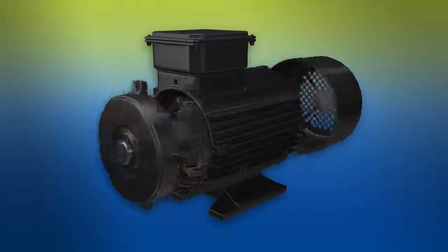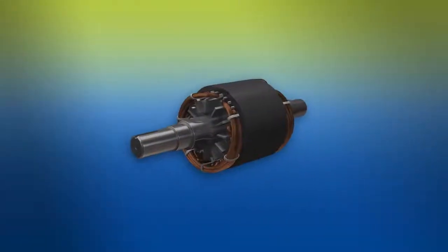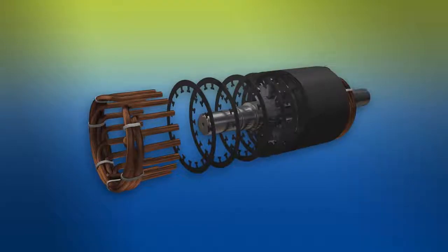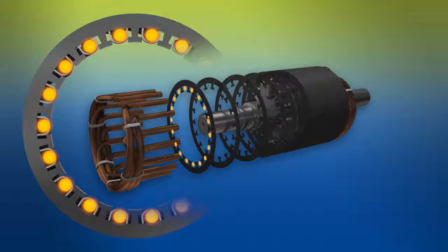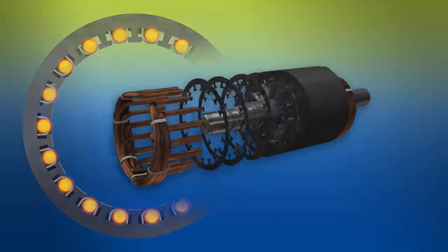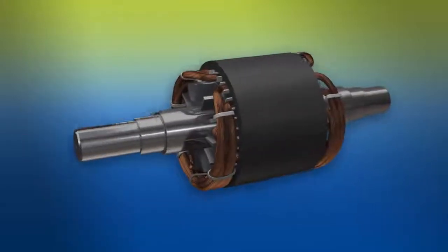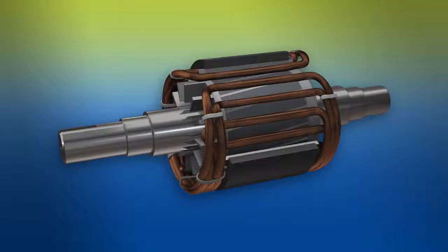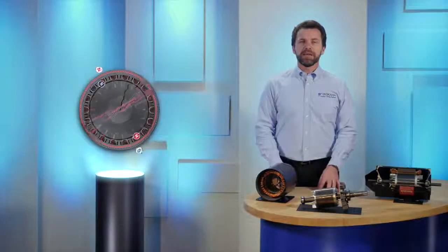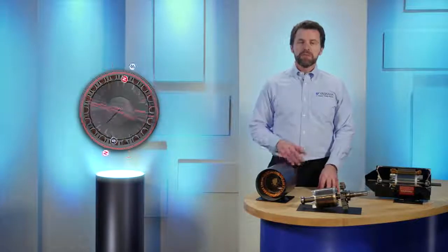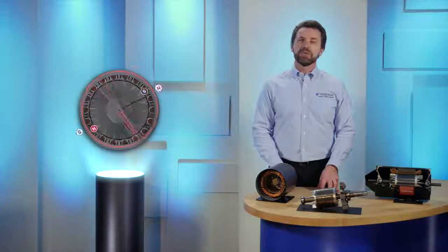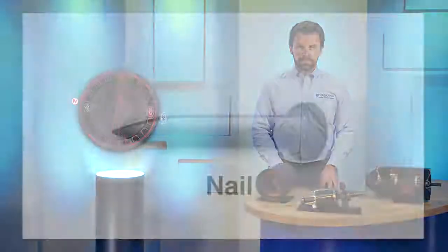As we described earlier, the stator has a core of individual laminated plates that are laminated together. These plates have slots in them, which allow insulated electrical windings to pass through the core. The stator windings are distributed around the stator in such a way that when current flows through them, the stator produces a magnetic field. To better understand how the magnetic field is produced, think about the electromagnetic demonstration you may have seen back in science class.